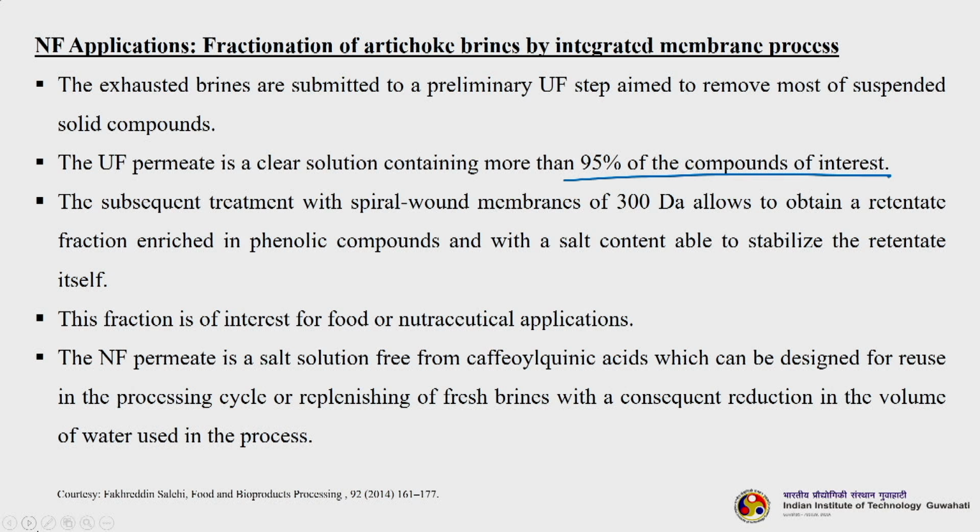So, the subsequent treatment with a spiral wound membrane of 300 Dalton, okay, allows to obtain a retentate fraction enriched in phenolic compounds and with a salt content able to stabilize the retentate itself. So, this fraction is of interest for food or nutraceutical applications. So, the NF permeate is a salt solution free from caffeoylquinic acid, which can be designed for reuse in the processing cycle or replenishing of fresh brines with a consequent reduction in the volume of water used in the process.